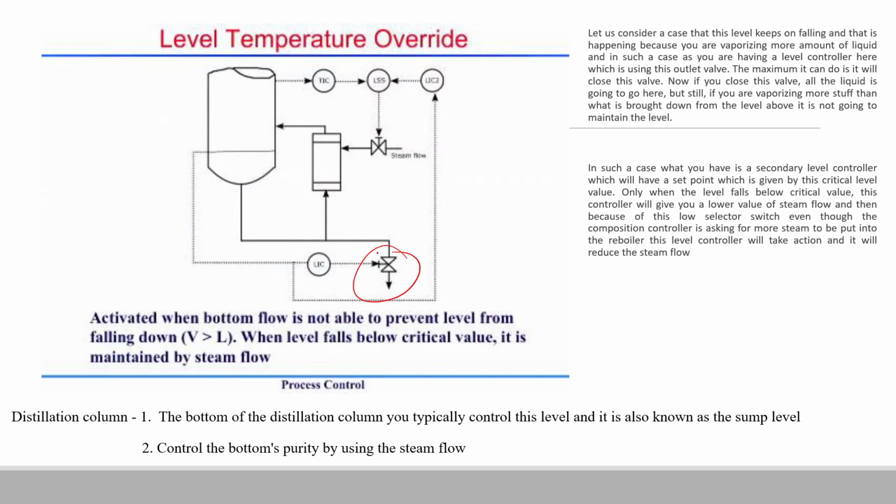And once we increase or decrease the outlet flow rate, we can see that due to the presence of this steam valve, the composition will keep on changing, or the vapors might keep on increasing. So once this level has decreased by some amount, we take this steam control valve into account. So this was the example discussed in the class. It was also related to split range control.